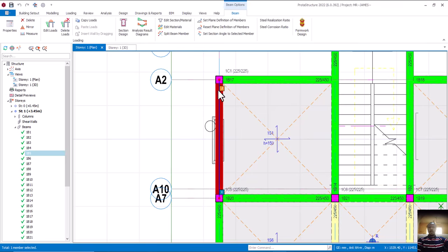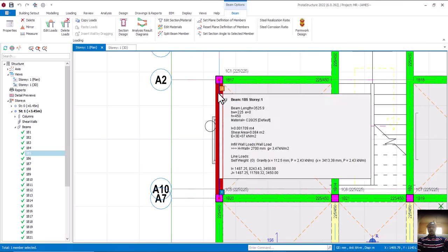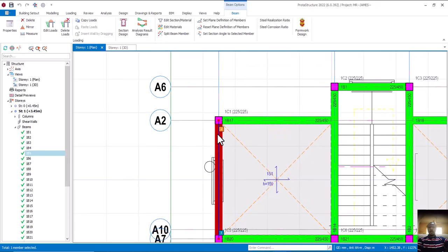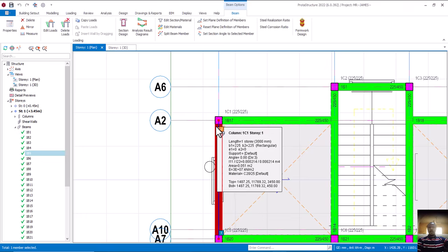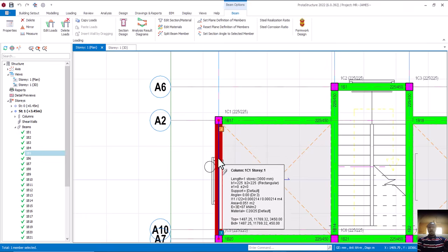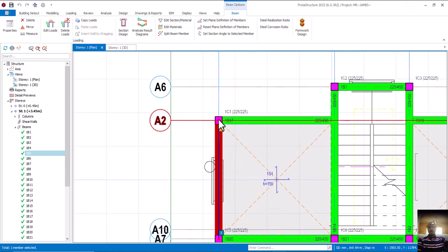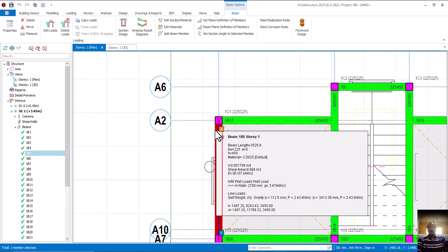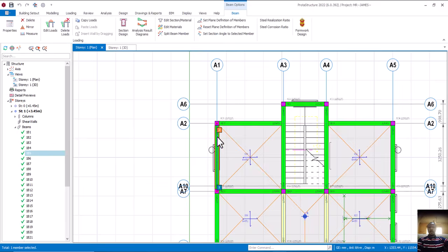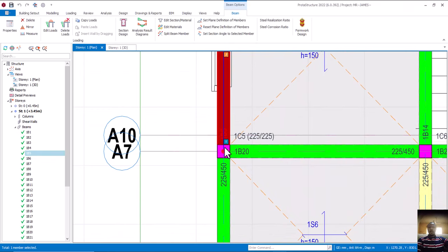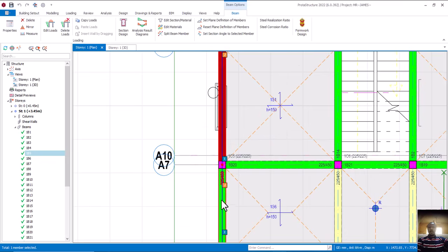But if you look at the J side, what do we have? This particular beam is ending on this column. Can you see? It's coming from here, coming to this place, and it ends here. There's no continuation. So at this point, this is a beam end condition at J, not at I, because if you look at I, after this beam stops here, there's another beam continuing. Is that okay?